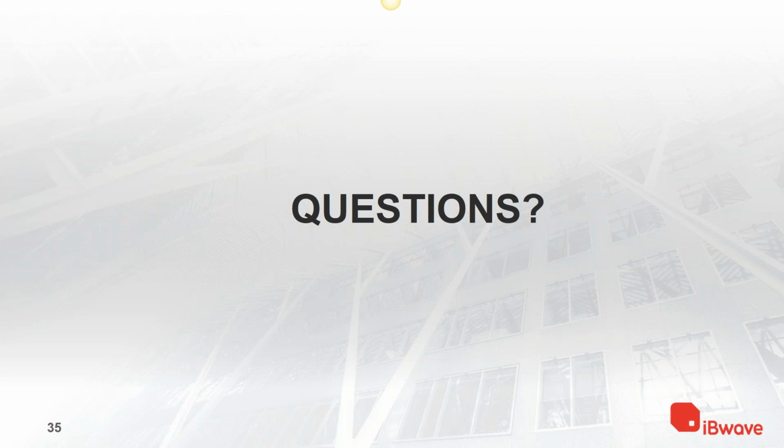Okay, so the next question is, how do you predict SINR? Well, first of all, you have to take into account that you have two different types of SINR. This is SINR in reference to PDSCH. Again, this is a question that comes from the LTE world. SINR in reference to PDSCH, which is a resource element that is used to carry data in LTE, and SINR in reference to the reference signal, or RS, which is basically something that is close to, let's say, a pilot signal in WCDMA.